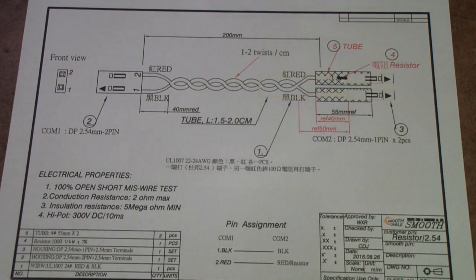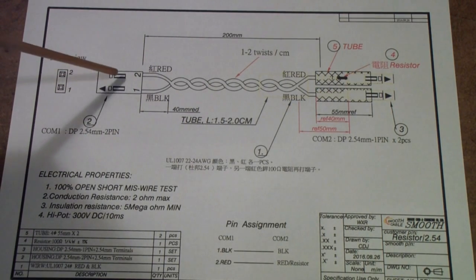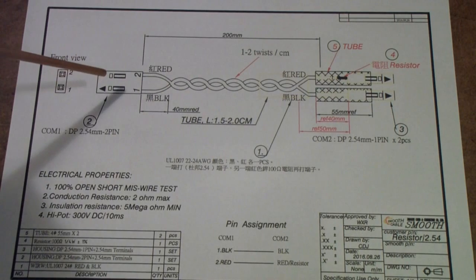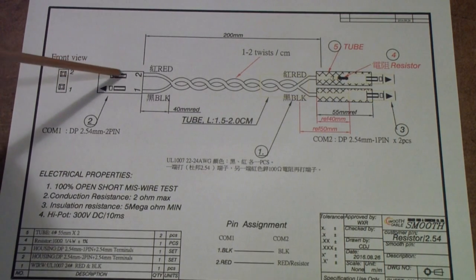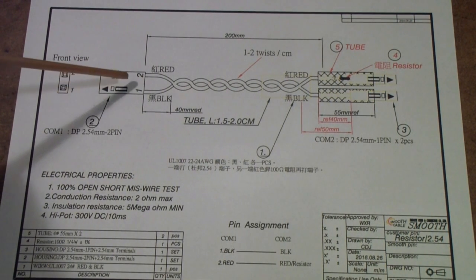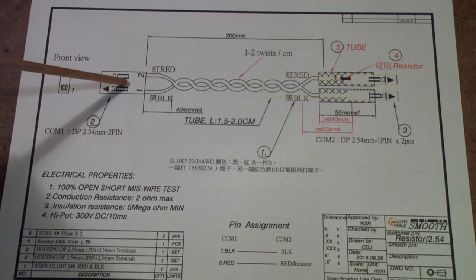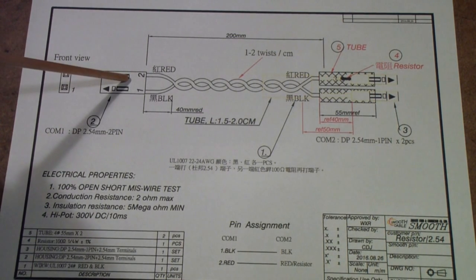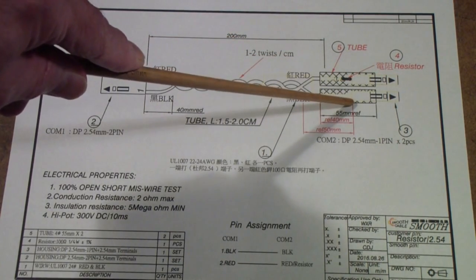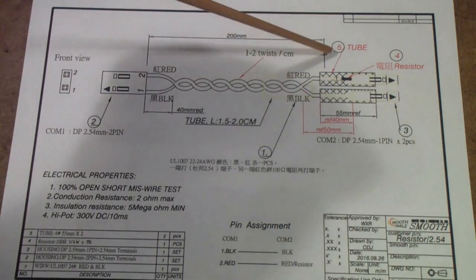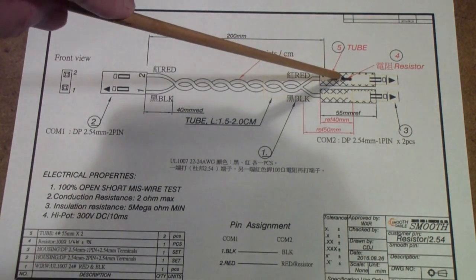Now, the high-speed adapter for the logic analyzer works with a group of these cables. I'll show you one in just a second. On one end is a 2-pin connector where the 2 pins are fused together. And that is the end that is supposed to be attached to the high-speed adapter. I'll show you that in a second. The other end of the cables are the ends that are supposed to be connected to your logic. And those are the ends that contain this 100 ohm resistor.